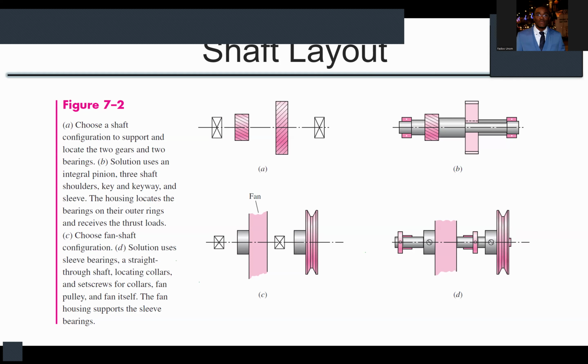Those are two configurations for your shaft. Usually, the inner ring is fixed firmly to your shaft, the outer ring is fixed firmly to the body, and then the balls or the rollers in between allow those two to rotate freely. Details on how that is attached, I cannot say now.